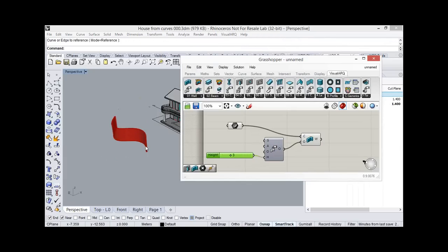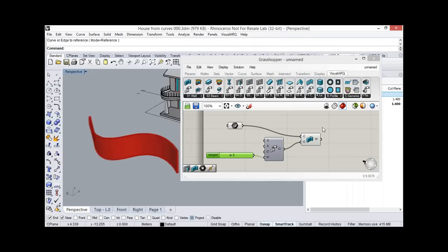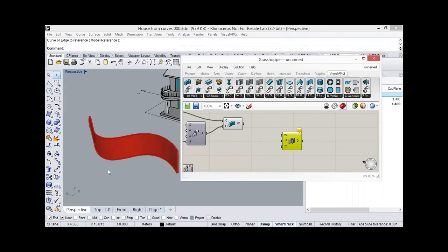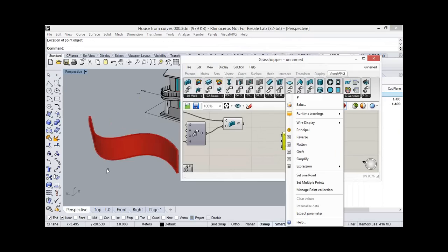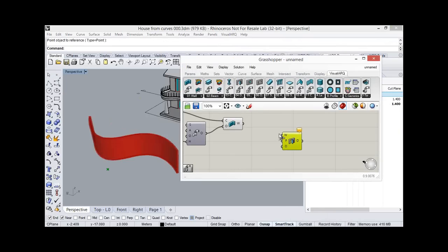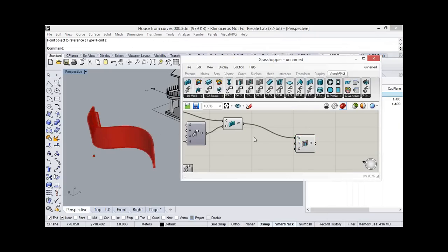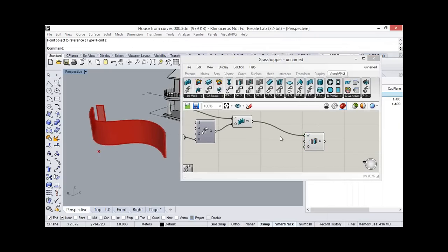Okay. So, if we wanted to create a door inside that wall, we need to place here a door component, which basically needs a point. So we'll set this point. It also needs the wall where it is placed. Okay. And we need to define the elevation of this door because it's placed above.